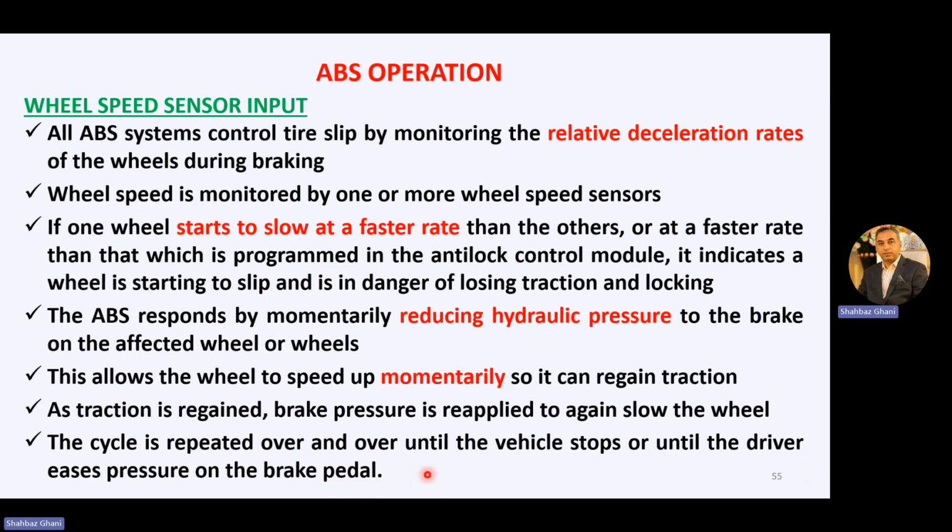So this is how the wheel speed sensor works. It gives the actual information to the control unit, and then the control unit gives signals to the hydraulic system, which maintains the pressure up or down to give the pulsation to that wheel.